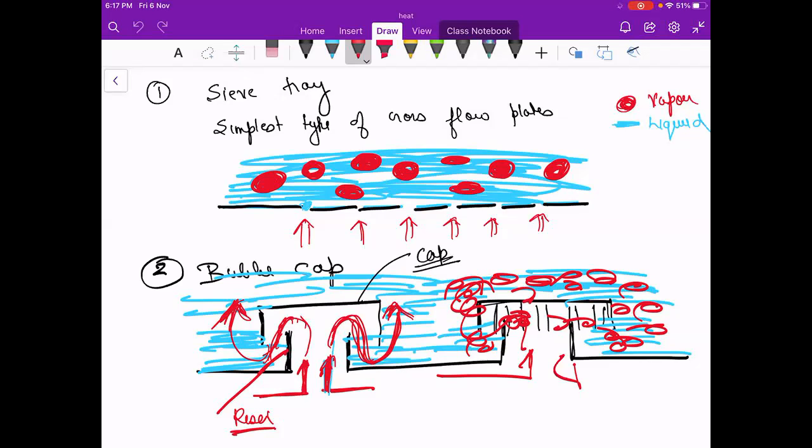Okay, so this is the thing. Here, gas is directly coming in contact with the liquid in the sieve tray. But in the bubble cap, the gas has to travel a certain distance. At a particular flow rate they will be going through that, so more bubbles will be created. That is why you can say it is better than the bubble cap.